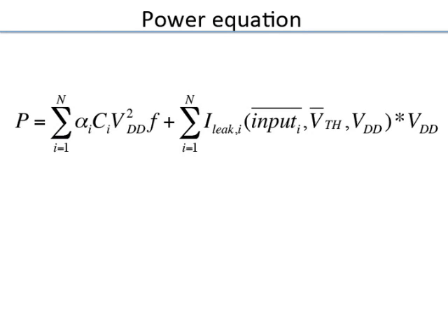Even though that gate is a CMOS gate, with a pull up and pull down stack, one or the other is supposed to be off, but the off one always will have some leakage. That leakage consists of subthreshold leakage, gate leakage from the drain to the gate, and then the junction leakage. So these are the main leakage components. And as we had discussed, the leakage in gate i depends on the input vectors to that gate. As we saw in the last class, for any gate, based on the input vector, the leakage currents can be quite different. So it really depends on that.